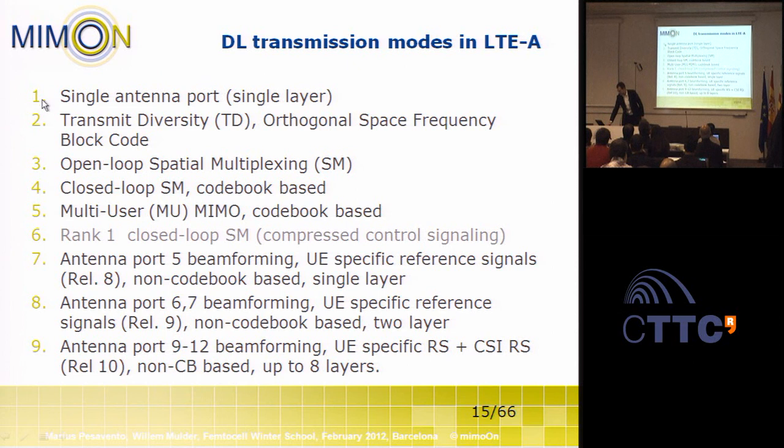That is transmission mode 1. Transmission mode 2 does not require any feedback of the channel state to the transmitter. This is based on orthogonal space frequency block coding.